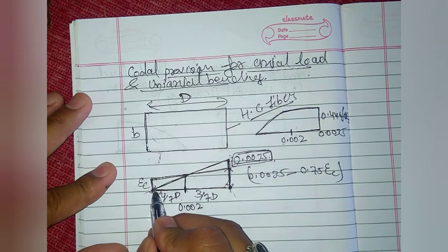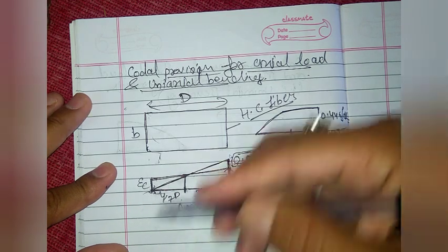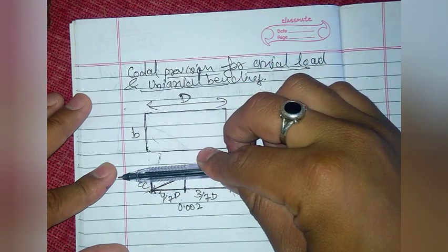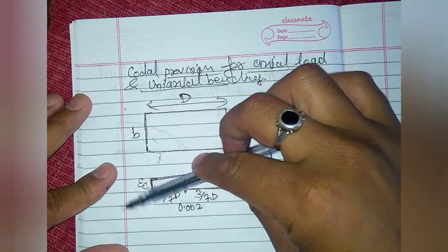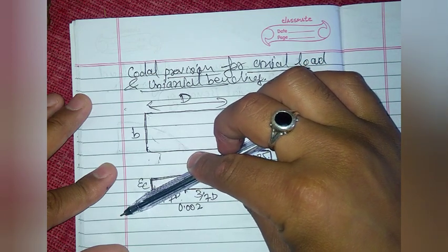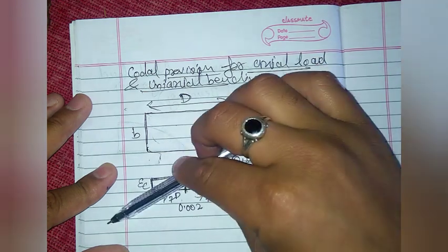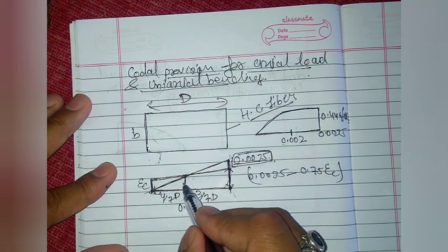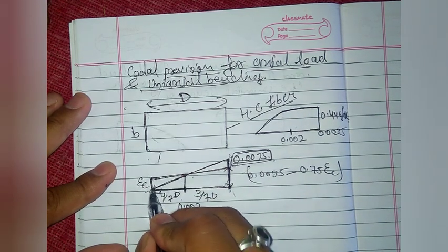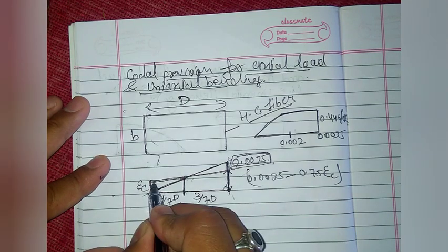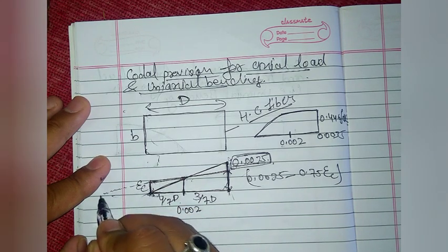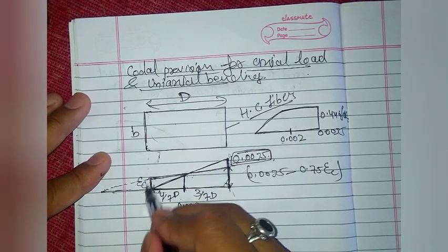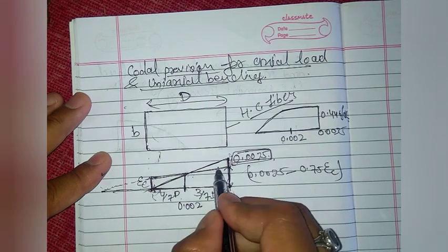Now you can see, when it starts to rotate about this point, we are assuming that the column section is such that this strain line is pivoted to this point and starts to rotate. So when bending acts in the column, the neutral axis starts to shift from here to here. Here in this case you can see the neutral axis has shifted toward this side.